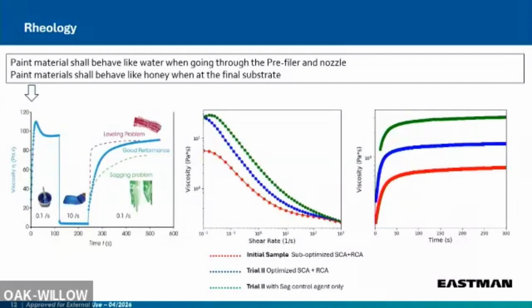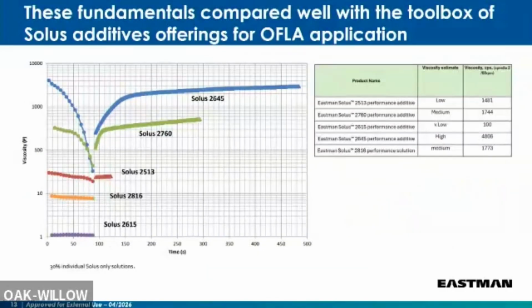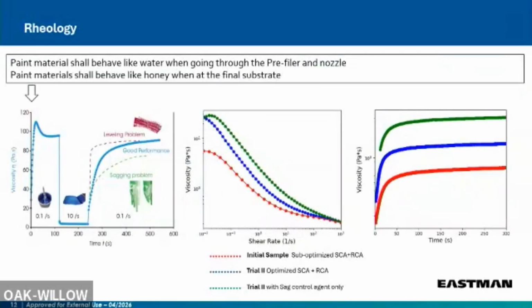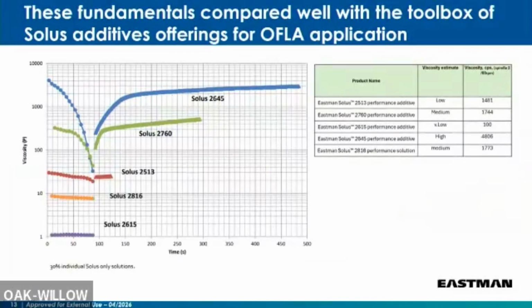Now, depending on where you are in your journey, if you are very high like this, then you need a rheology modifier, and you need to commit here somewhere, in this range. But suppose you are already here in your formulation, the part A, where you are using your SCA, and you just want to fine tune it, then maybe you don't need such an aggressive one, you just need to go to one of these rheology modifiers. But if you are way down and you really want to take it high, then you may have to go here, to this sort of rheology modifiers. So you need to quantify that. You need to measure where you are first for your rheology.